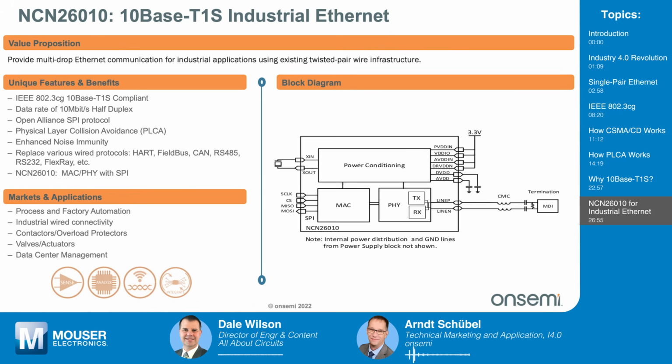And that basically, extending the range and extending the number of stations helps you, again, cutting down costs, because figure if instead of 8, you can now put 32 stations on a 25-meter cable. You wouldn't need 4 segments. You only need 1 segment. So that saves you a switch port at the other end. So that's basically where another saving comes in. More stations on the same cable gives you a higher cost saving. You could use that MAC-PHY together with a low-cost microcontroller and turn this into a sensor node.